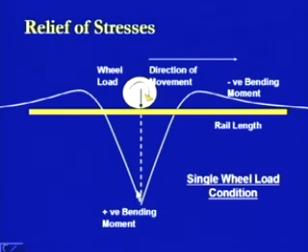Because of the curvilinear nature of this bending moment, it goes something like a little straighter or exponentially this way. There is a point of contraflexure at this point, after which there is a change in the sign of the bending moment. If we take this bending moment as positive, then obviously this bending moment is negative.